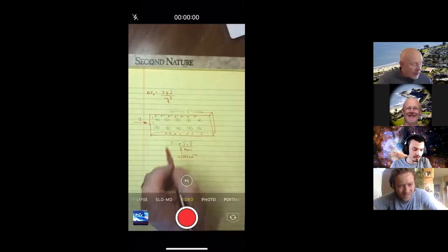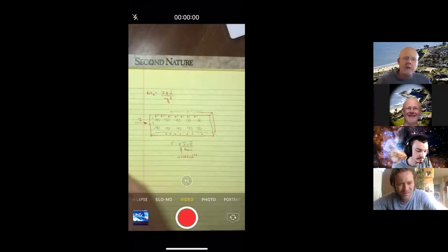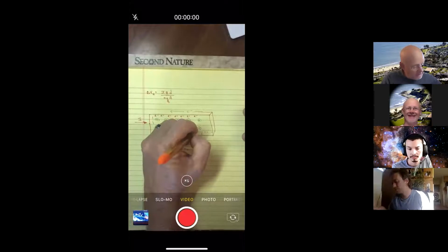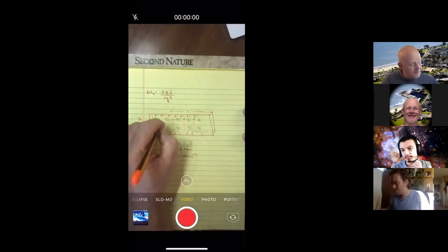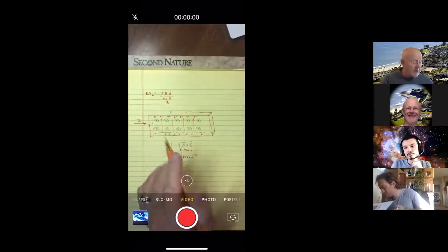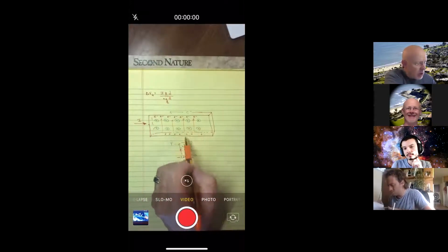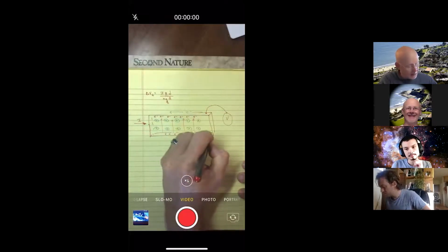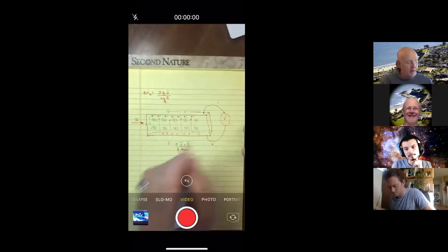Okay. And so then what's going to happen is a field is going to build up. The electric field will build up in this direction. And that electric field wants to pull the electrons down. So the bottom line is a few electrons go up real easy at first, but then as they start to pile up, they keep other ones from going. So there's an equilibrium established. And so what happens if you took a voltmeter and hooked it on the top and bottom of this copper plate, you would pick up a higher potential here than here.